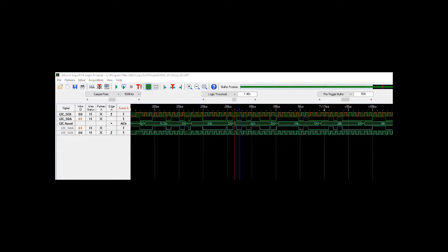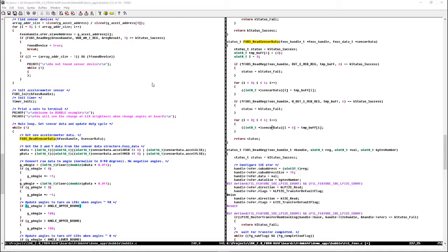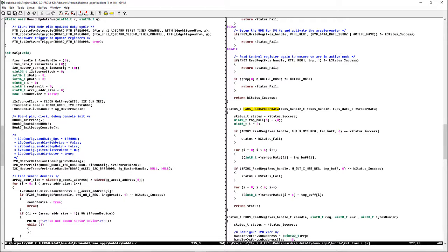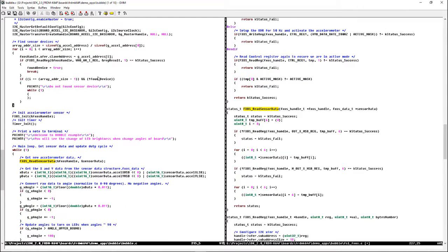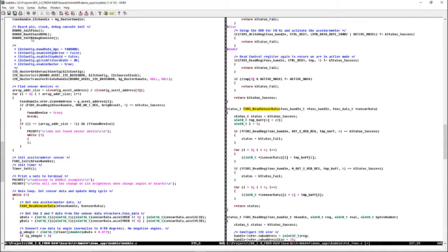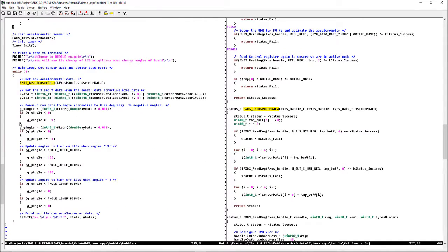One thing we can do is look at the source code. If we look at the source code that comes downloaded straight from the NXP site, this is an example called Bubble. This file right here has the main, in the file bubble.c. This is where all C code starts. You don't really need to know C code to follow along with what we're going to do on Embedded Apprentice. It doesn't hurt. We do some setup. We initialize things, set up the I2C bus, and then while(1), which means loop on this forever. So we're going to execute this code over and over again.